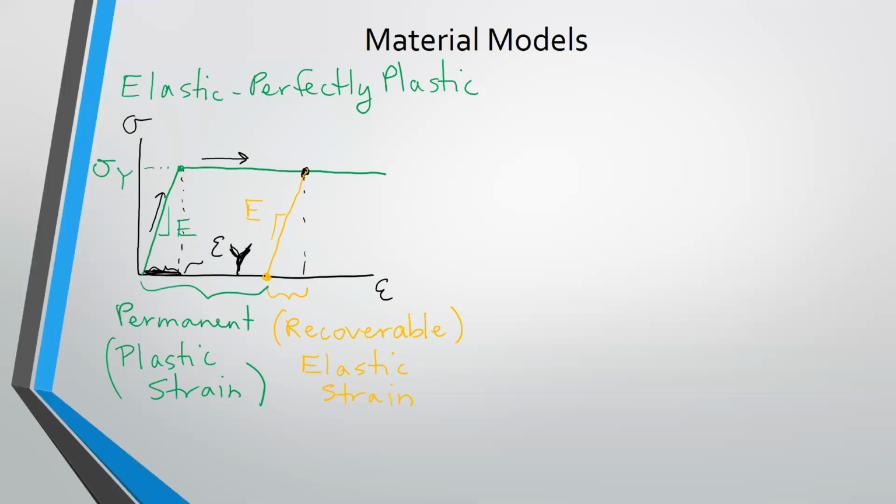But it's extremely important to me that, despite the fact that in this model they have the same value, you distinguish between the two. The yield strain is not the same thing as the elastic strain. The elastic region is the region prior to the yield strain, which means that if you're in that region, you're behaving elastically. Once your strain exceeds that yield strain, now you're behaving plastically. And numerically, they might end up being the same answer, but it's very different.